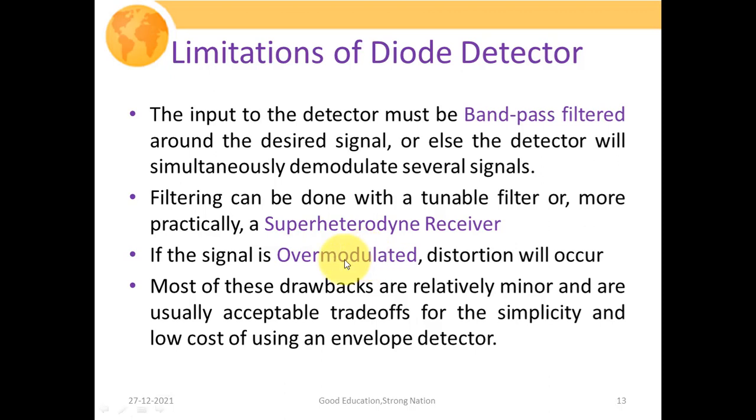What I want to mention here is, if we are using this diode detector circuitry and our AM signal is over modulated, then we are not in a state to obtain that signal value which lies below the conducting voltage of the diode. If some message lies there, we will definitely lose that information. And if we lose a certain amount of information, then obviously distortion will occur, or we could say that we are not in a state to obtain the actual information signal back.